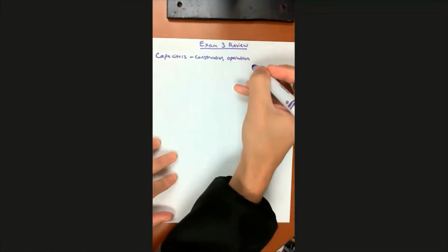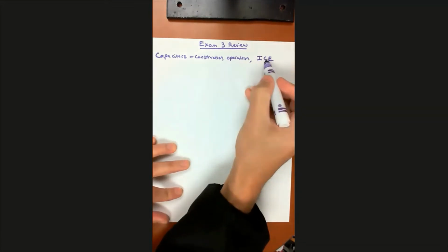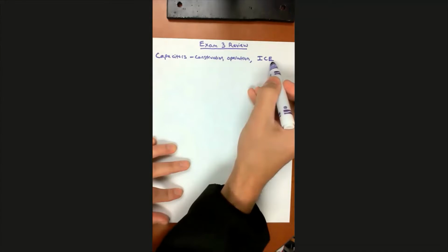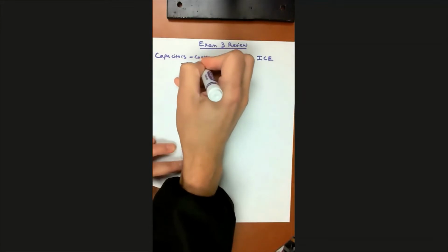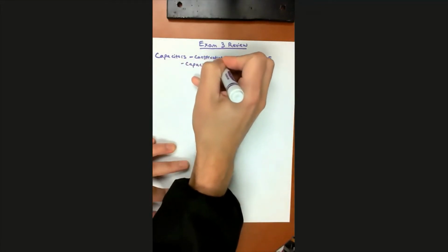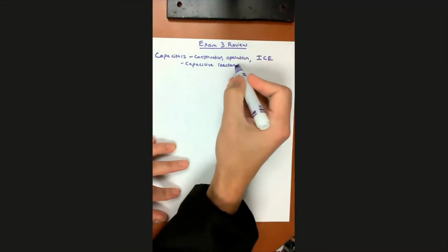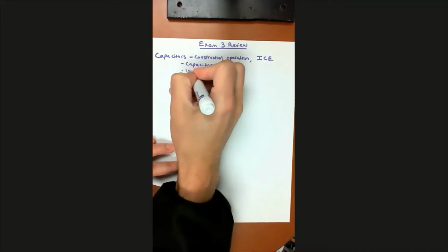basically their operating principles. Remember the mnemonic device ICE, where we said in a capacitor C, the current I leads voltage E. We also talked about capacitive reactance and what reactance is and how to calculate it. There's a formula here for capacitive reactance. We talked about impedance